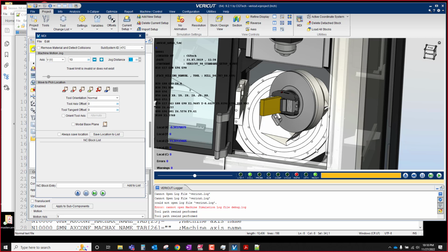And if there was an error, it wouldn't take more than about 8 or 10 minutes for it to say, oh, there's an error, kick this part out. It would flag this pallet and pull it out of the system. We're going to load another pallet, scan it, build everything in the background, toolpath it, simulate it, verify it. Everything's good. Okay, now we're going to run it. We're going to cut it. So literally the most they were losing is maybe 20 minutes in an unattended shift. Dude, it was slick.